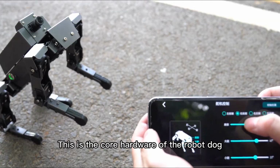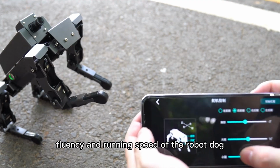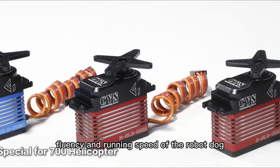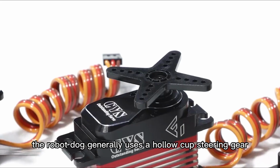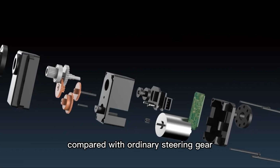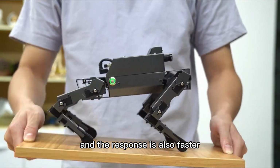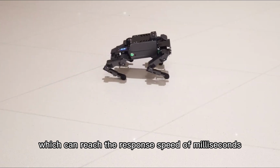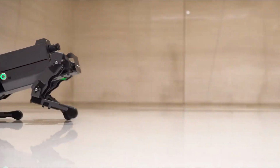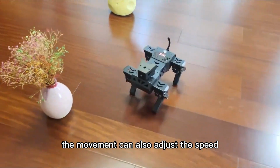Robot dog joints, steering gear. This is the core hardware of the robot dog, which determines the stability, fluency and running speed of the robot dog. The robot dog generally uses a hollow cup steering gear. Compared with ordinary steering gear, the rotation speed is much faster, and the response is also faster, which can reach the response speed of milliseconds. At the same time, the movement can also adjust the speed.